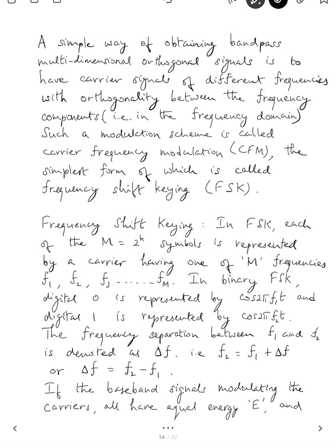So we transmit the 0 as a carrier signal of some frequency called F1. So it is cosine 2 pi F1t, and it has some amplitude. And the 1 is transmitted as another frequency, which we can call cosine 2 pi F2t, again of some amplitude. So the two signals are differentiated. That means the 0 and the 1 are distinguished by virtue of the frequency of the carrier signal. So if the received signal has a frequency F1, the receiver will interpret it as a 0, and if the received signal has a frequency F2, it will interpret it as a digital 1.